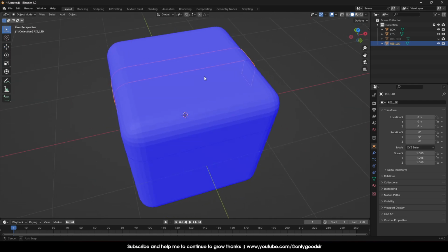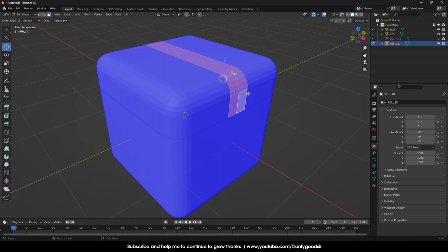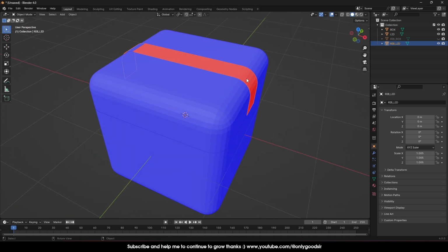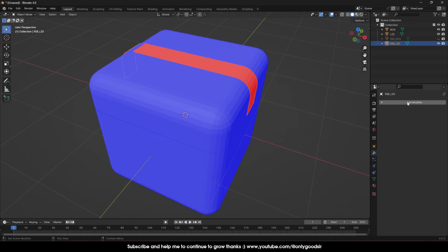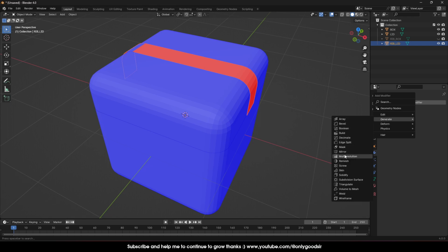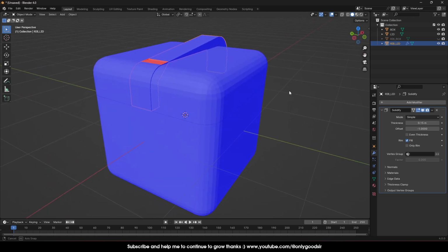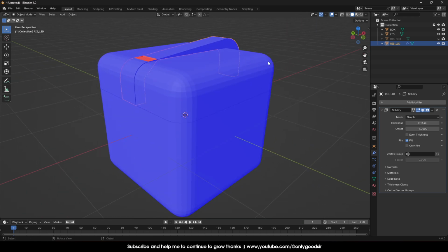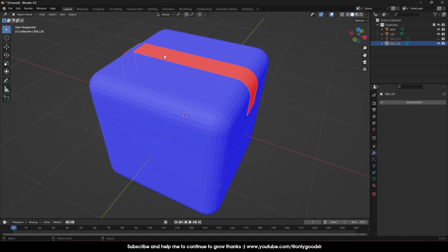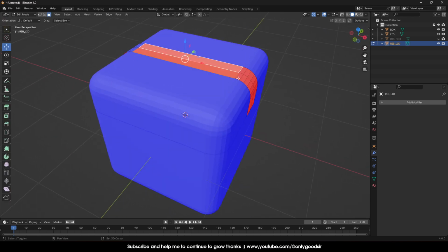If you don't fix that, if I undo this and go back to how it was, like this, and say I want to solidify this, you'll get some funny behavior. So go generate, solidify. You can see what I'm talking about because the faces are not all facing the right direction. The solidify won't work correctly. So yeah, that's one to note. I noticed it on 4.